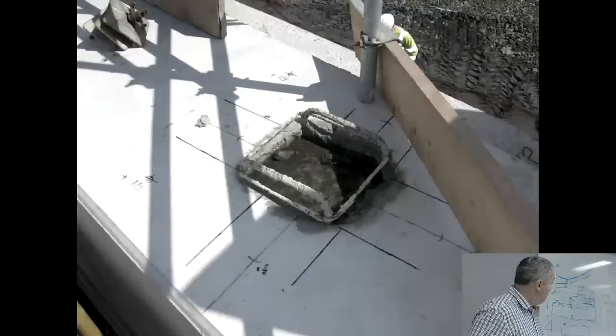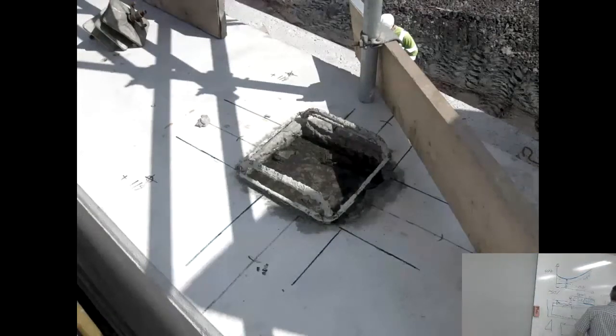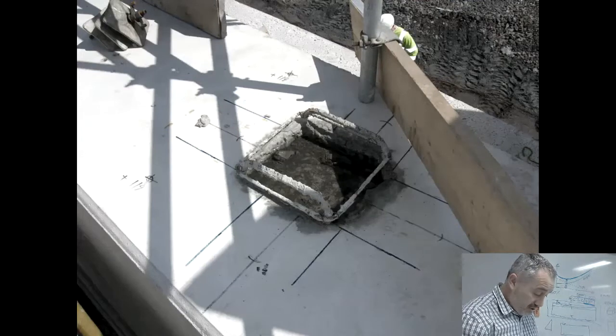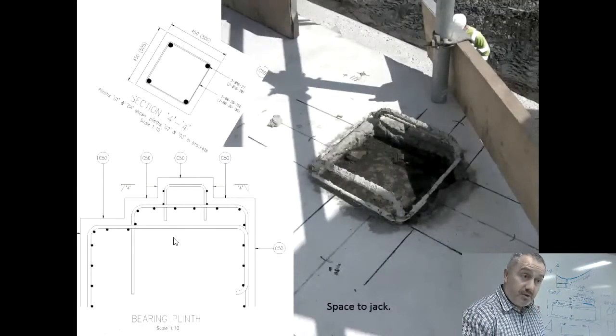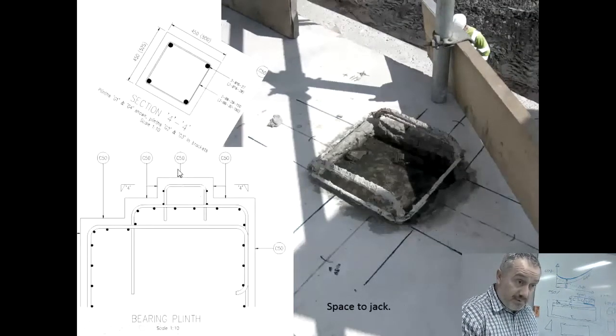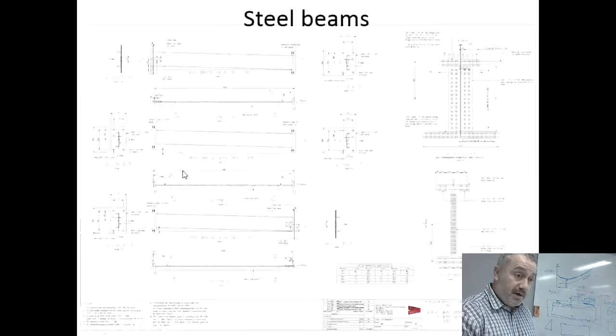And then on top of the retaining wall embankment, we've got the connections that we're going to be putting our bridge onto. So you've got the detail there. So there's the top of the retaining wall, and then we've got our reinforcement, and again you've got the C, which is representing our cover, and it's like a little plinth which will be spaced to jack up the bridge should we need to replace the bearing.